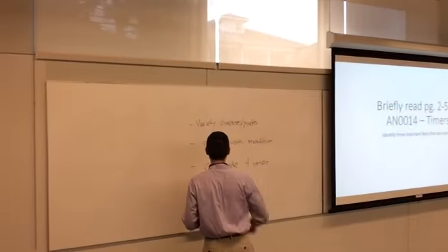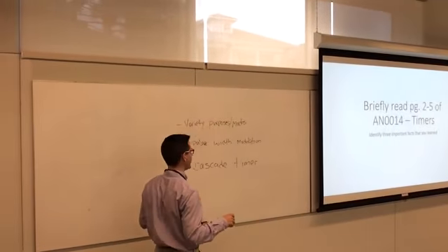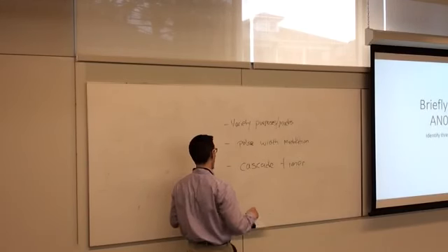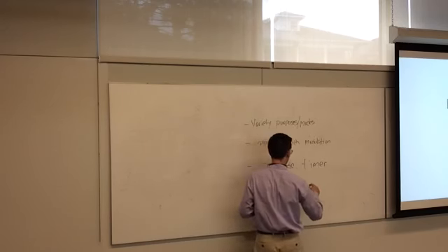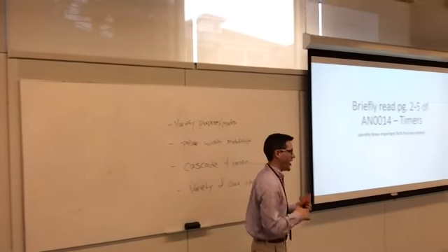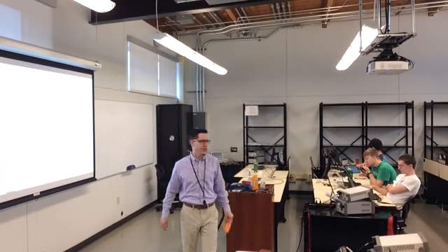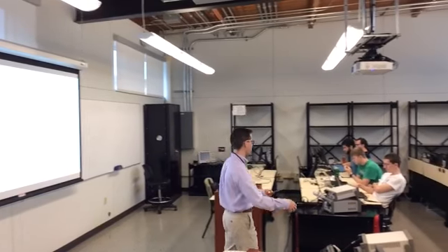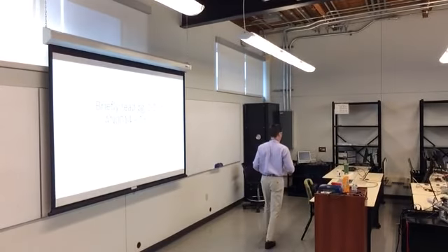All right, Jason, one last thing. What else did you find out? Something we don't have. Right, that's another important thing. Your timers can have a variety of clock inputs. You can drive the timer from the internal clock, from the peripheral clock, from an external clock. There are 4 or 5 different sources that you can drive the clock from. You can scale all of these clocks. There are a lot of options when it comes to timers, because timers are used almost everywhere inside of your microprocessor.